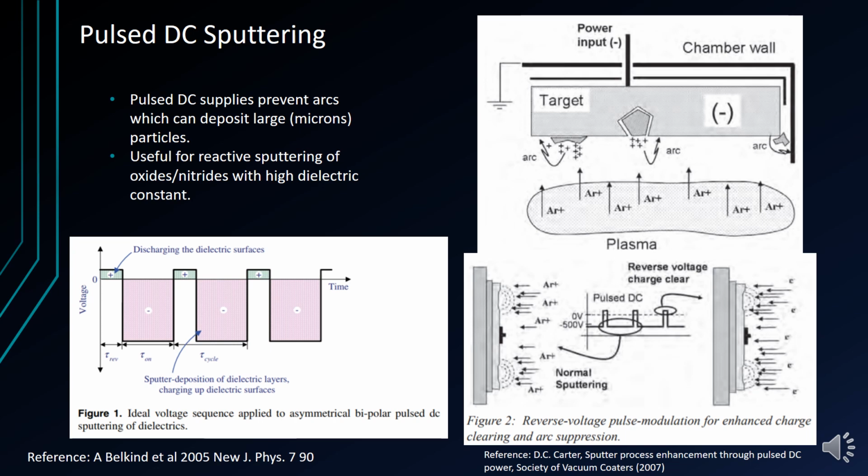The dielectric sputter system is equipped with a pulsed DC power supply. This is particularly suitable for reactive sputtering of dielectrics. During these processes, islands of reacted material can form at the target surface, which can charge up, eventually leading to breakdown to surrounding metallic material.